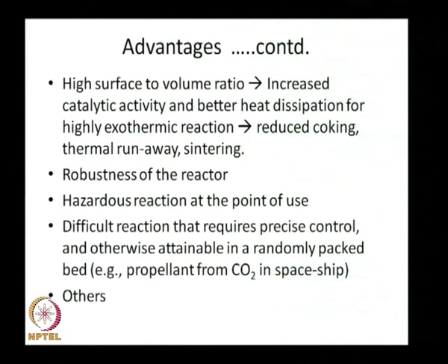Okay, advantages continued. When we go for a microstructured catalyst, as I said, instead of having a randomly packed bed, you can have a monolith, something like a honeycomb with internal walls coated with a catalyst, that we call a structured catalyst. There you can have a high surface to volume ratio, which means increased catalytic activity and better heat dissipation for highly exothermic reactions.